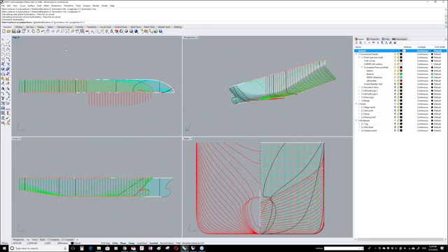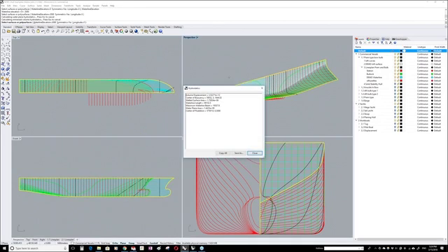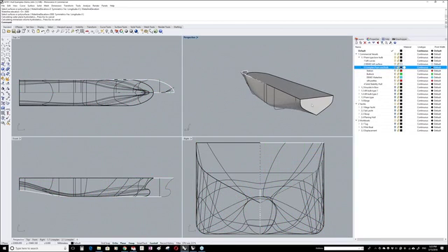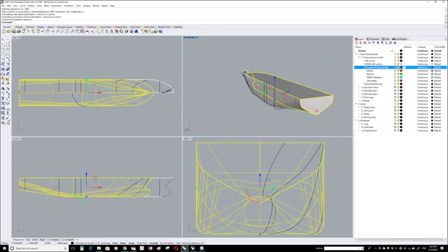I repeat with my right mouse button, and I type in a waterline elevation. I have to choose it below the height of the open mirror, the stern, because the stern is still open. So about 3000 should be okay. I click on it, and then you get the hydrostatics. And if you want the hydrostatics of a draft where the mirror is on the water, then you should make a closed stability hull, which I've made here. So you have to make a stern and a deck and close it completely, and then you can use hydrostatics for all the drafts that you want.